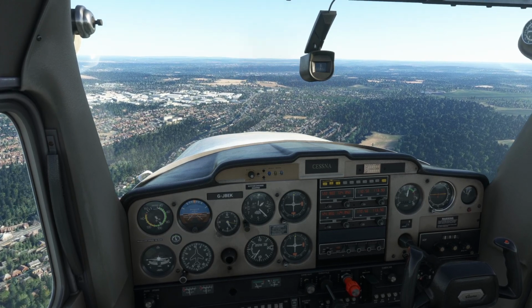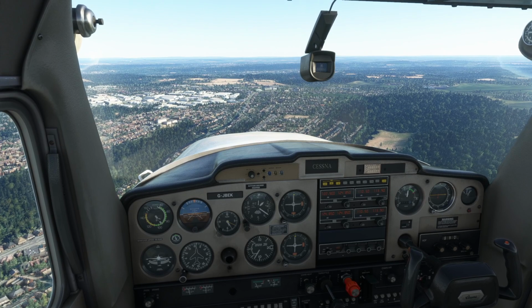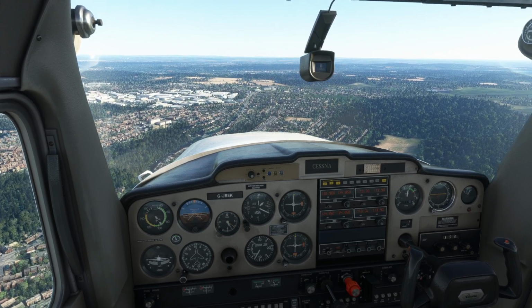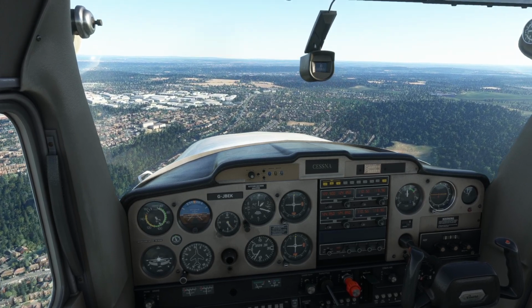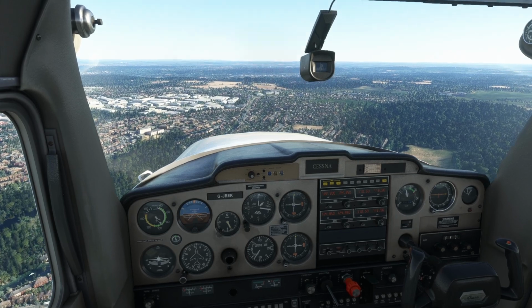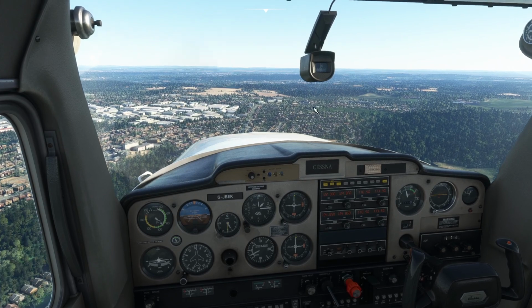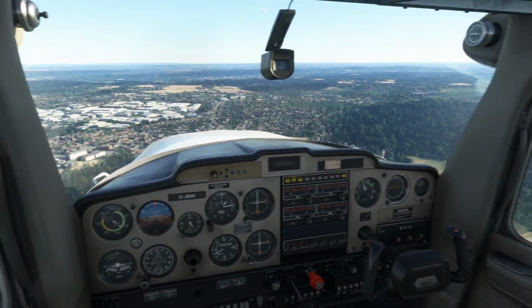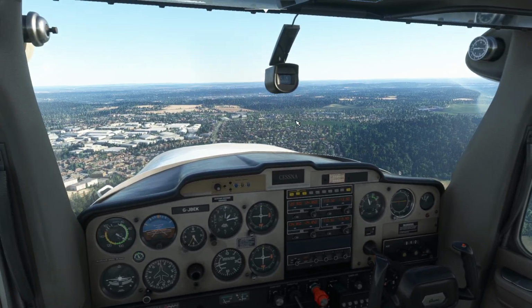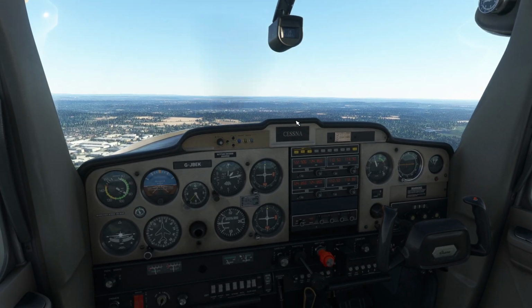It doesn't help we're travelling into the wind now, so our speed over the ground is less than our indicated airspeed. So we're trying to get the speed down in time and drop to 1,000 feet on this leg, and then we make the turn at the appropriate height to see the VASI lights. So let's go and sit down in the cockpit so we can see under the edge.